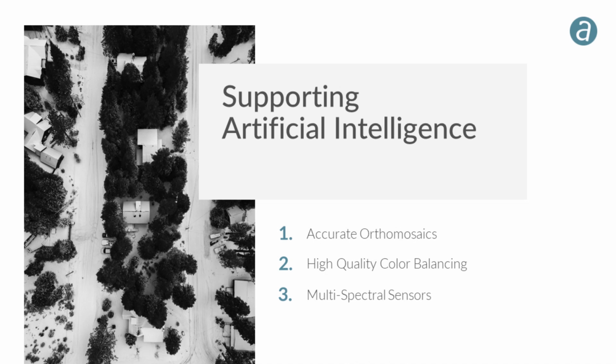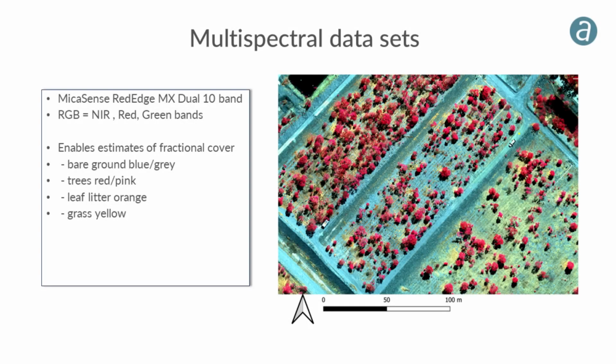So the good thing about Correlator 3D is that you can readily align when you process each date's data sets and you have ground control or good RTK, then they pretty much fall on top of each other, which is really handy for multi-temporal stuff. Also, the color balancing means that the color of the objects of interest tend to be constant if you're capturing data at a similar time of day.